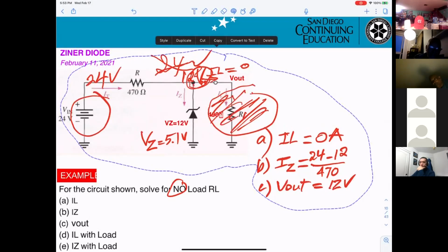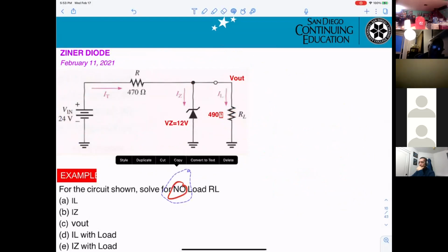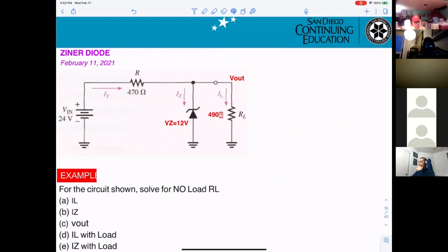But I want to make sure everyone can follow what we're doing now. There's a voltage regulator that has a variable output, between maybe 5 and 10 volts, versus a Zener diode that's only set for a specific voltage, correct? You cannot get a variable. Right, if you want variable, you have to get something else.